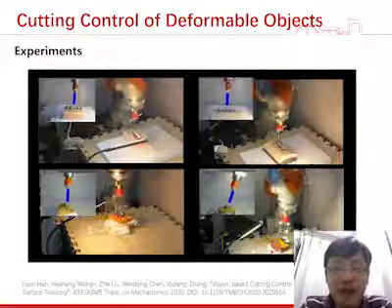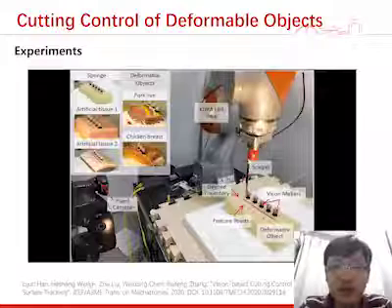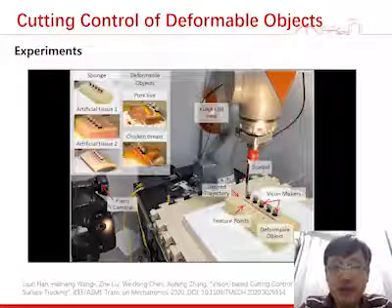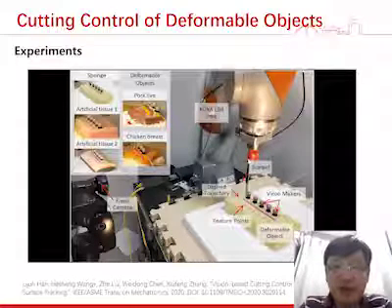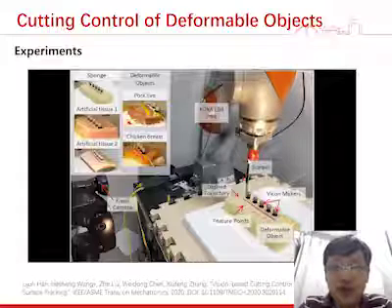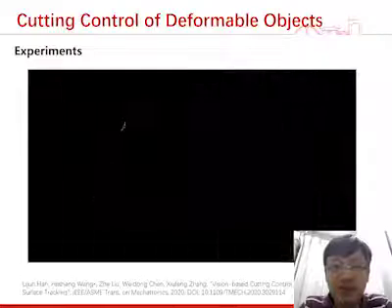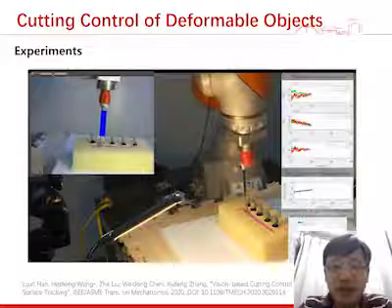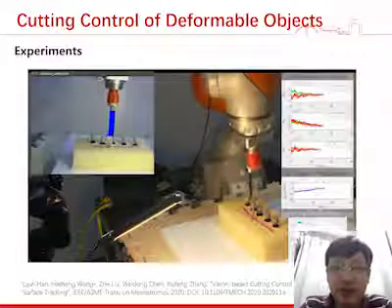In the image plane, the blue region represents the desired trajectory, which was calculated by the trajectory point of the deformation and the desired cutting depth. The green one was the projection of the knife extracted from the image and represents the current image features. The cutting task transformed to the image plane is to control the knife, the green region, to track the target surface formed by the motion of the blue region. We say that the controller has good tracking performance, and the experiment result proves the proposed algorithm can realize the automatic control cutting.